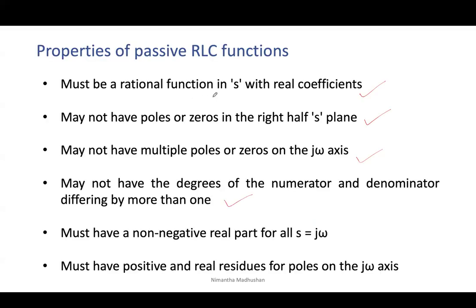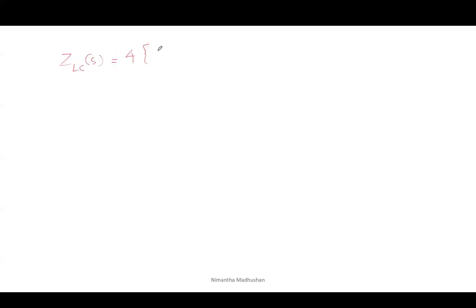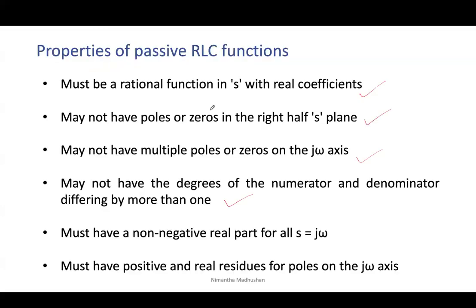Now I will write the function again. Z_LC of s equals, expanding this function, (s to the power 4 plus 17 s squared plus 16) over (s to the power 3 plus 4 s).